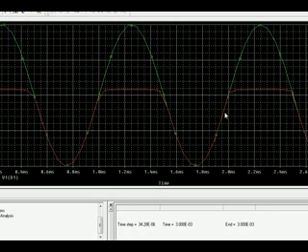Half the rectification will be done here. So now what is happening over here? The diode turns on at a voltage which is about 0.7, and it remains on. So when it's forward biased, it will remain at 0.7 volt, and in reverse bias it is in the off condition, so it will get the voltage similarly. So we'll get the negative voltage as -10, but the positive voltage will remain at about 0.7.